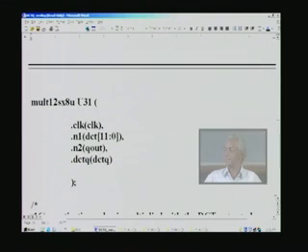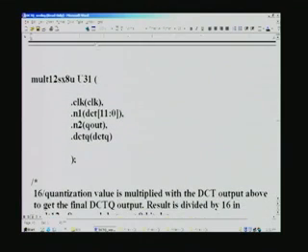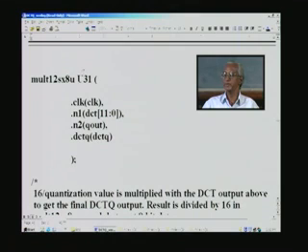So, after invoking that ROM, we need to multiply in order to get the DCT queue from DCT. One input for the multiplier will be the DCT, which we have already seen, and Q out is nothing other than the 16 by quantization value, which we have just seen in the ROM, and that is being fed here. You will appreciate the feature of calling ports by name here, because right now you can see all this. And earlier, right at the beginning, I mentioned that we have declared this as a wire here.